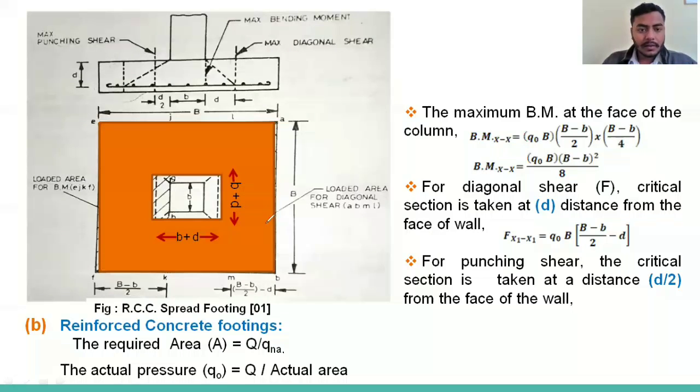I said this portion will come to this dotted line. Except for this colored portion, everything will remain in position, but this portion will go down. Means the column with this footing will go down, and at this edge and this side, there is a punching shear. The shear is developed.